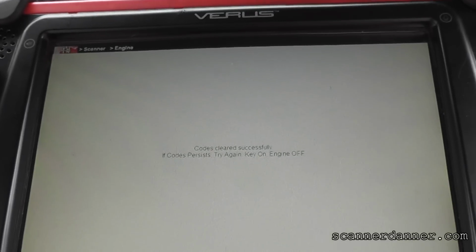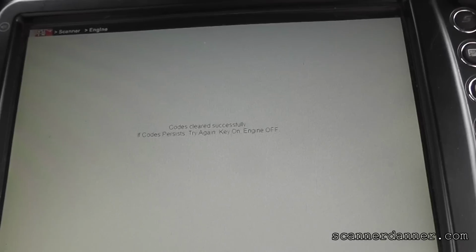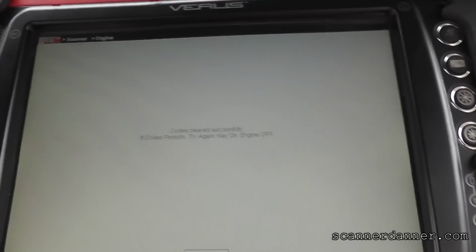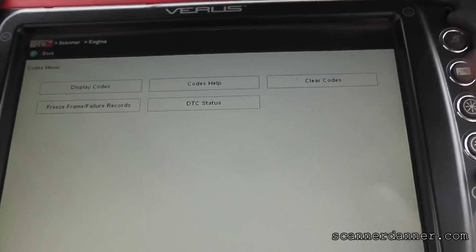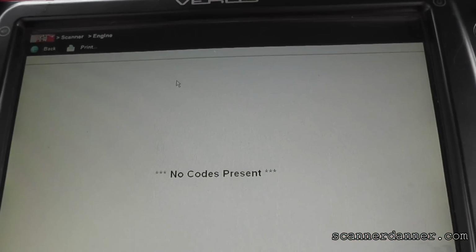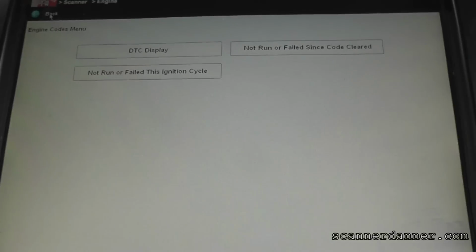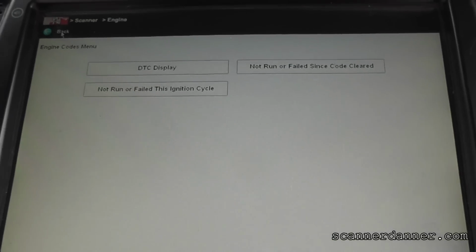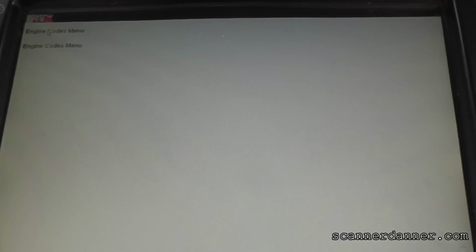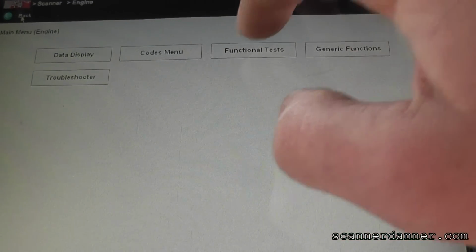Signal circuit integrity, that's the chapter I'm thinking of in my book. I think it may be chapter 10 or 11, where I do signal circuit integrity testing. That's really what I'm doing here. This is with my test light there. Notice the code's gone. Again, I'm not worried about our wiring here, guys, at all. What I cannot explain to you is why that bias voltage increased. But what I will be able to show you now is this actuator test. Go back to functional.